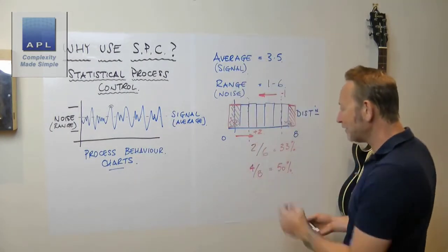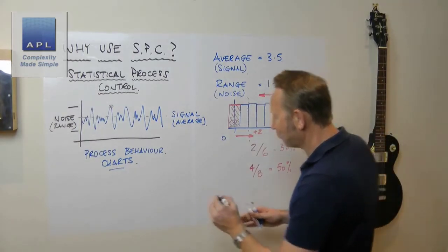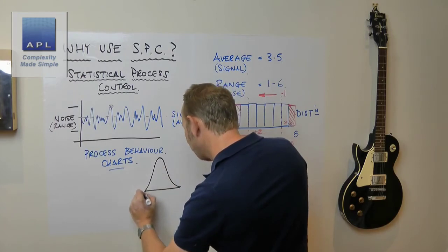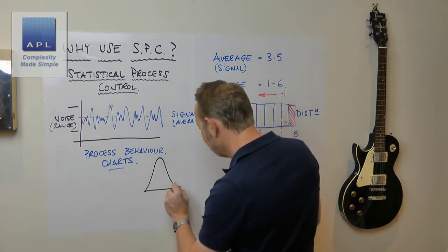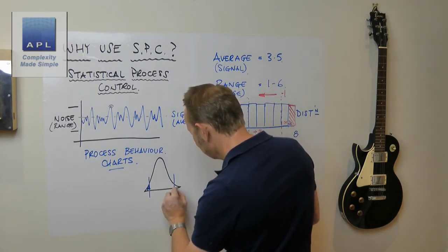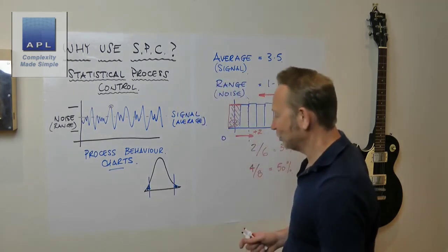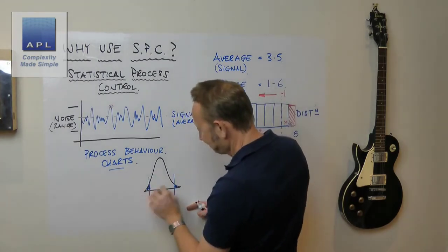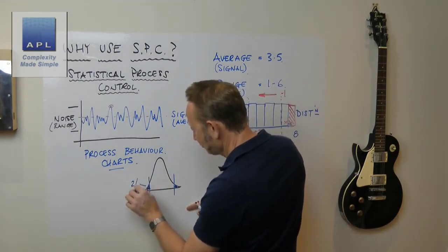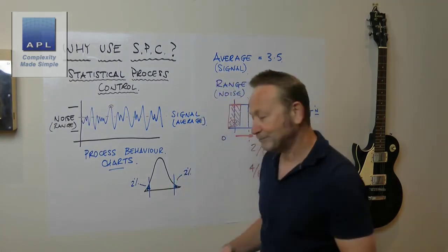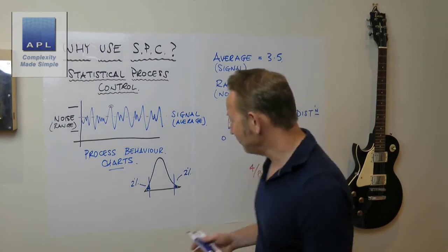Now, of course, the pattern that is happening out on your manufacturing process isn't a uniform distribution. It's typically a normal distribution. And maybe you've got this situation. And of course, what the operator will do, look, maybe there's 2% defects in that tail, 2% defects in that tail. What will they see most of the time?